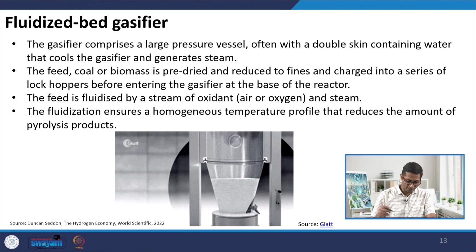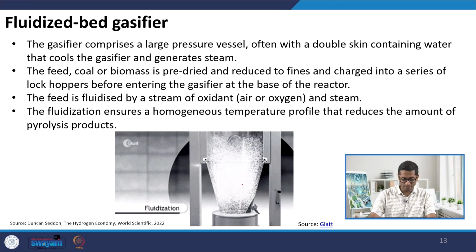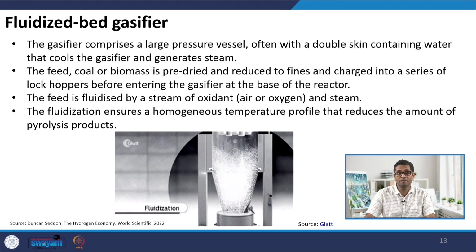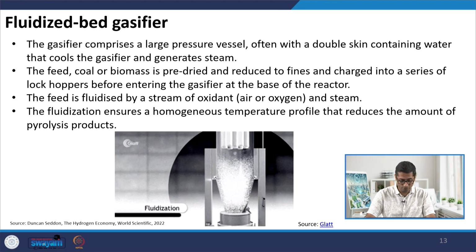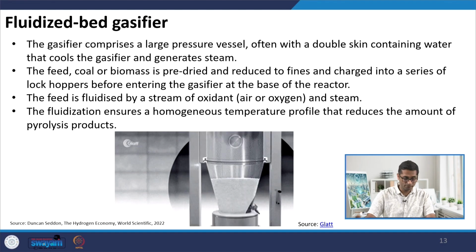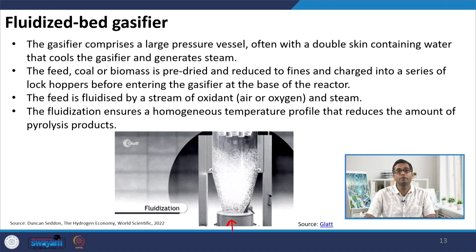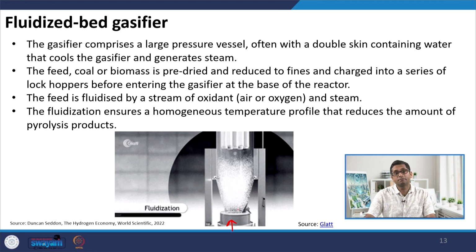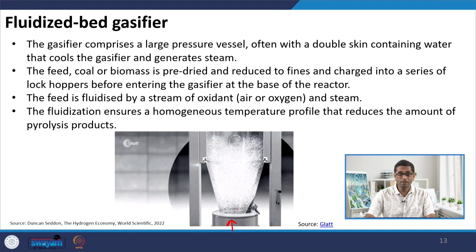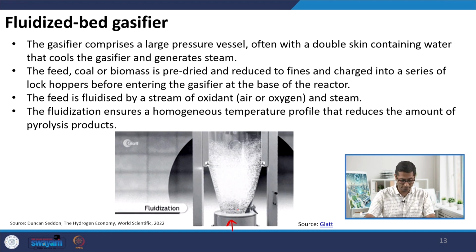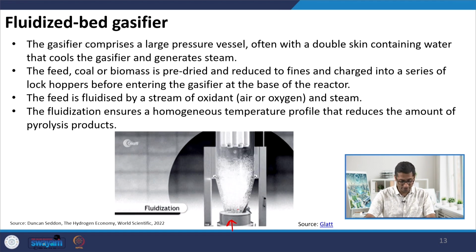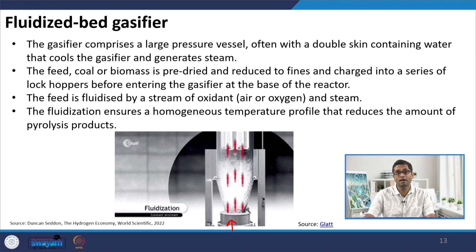So imagine that this is formed from the coal and some kind of bed material which could be sand or silica in nature, which does not react with coal, and then there is an oxidant which could be oxygen or steam coming from the bottom of the gasifier, and this would be coming at a very great speed, and the speed would be such that this bed is going to act almost like a fluid. So this is what I call a fluidized bed regime or a fluidized bed gasifier, that the solid particles of coal and the bed material are made to act like a fluid.